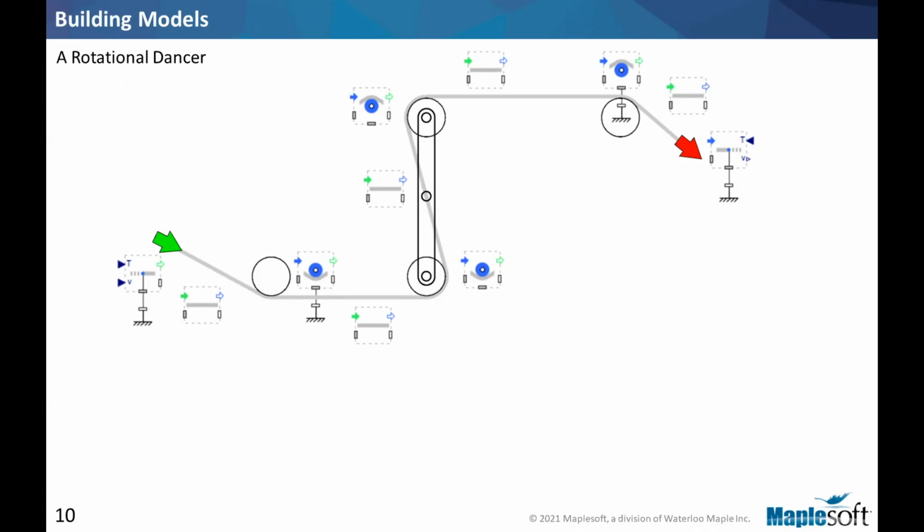So what else? We have anchored most components, but we still have 2 idler rollers that are not connected to anything. We need a pivot so that we can connect those 2 rollers to that, and that pivot exists in the primitives. So we have a revolute joint, which in this case will be our pivot.